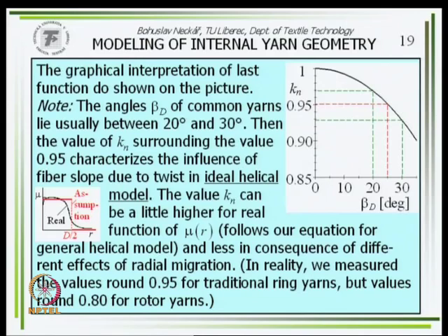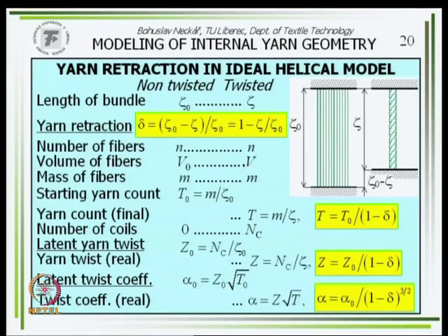No, for rotor yarns we obtain much smaller value because the angles of fibers are not the dominant effect created through twist, but important is also the intensive unparallelity of ribbon and rotor, and so-called bridge fibers on the periphery of rotor yarn. You know this term, you know this problem. So in rotor yarn, the coefficient Kn is smaller.